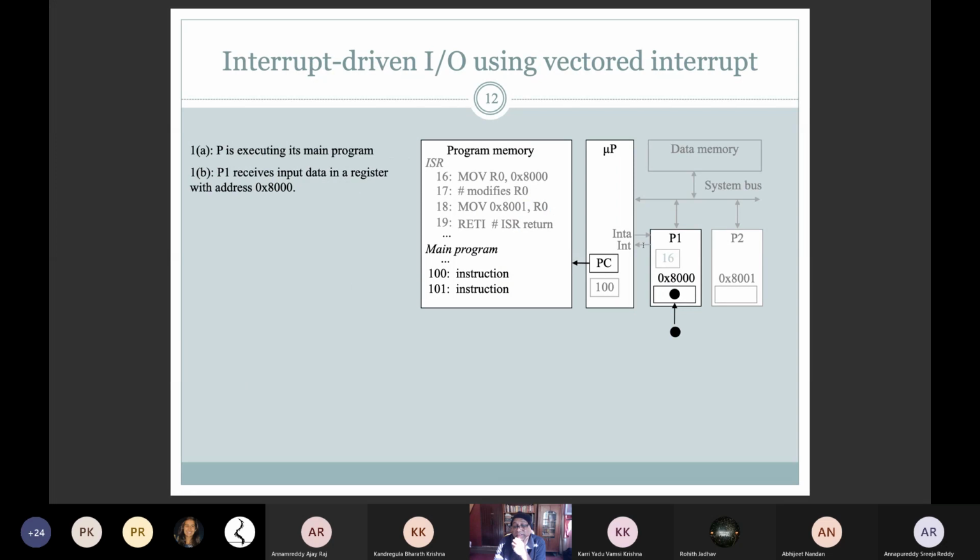So this is known as interrupt acknowledge. That means whenever there is an interrupt, it has to acknowledge. After that, the address of the subroutine should also come. That means it occurs in two steps. First step, it will do the interrupt. Then second step, it will get the address. This address of the subroutine has to come from the external device.